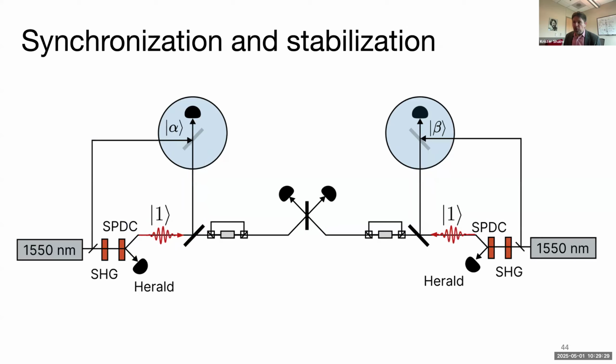So I'm just going to wrap up and hand it over to Nick here in a second. I just want to mention that the last major challenge, which sets up a lot of what Nick will be talking about, is that our system needs to be very well vertically integrated. Because this protocol is phase sensitive, we really wanted a system where you could derive a local oscillator and your down conversion from the same initial system.